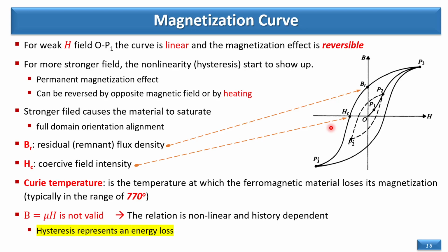Why? Because heating will cause a lot of strong random motion, and the arrangement of atoms in domains and the alignment of those domains with the externally applied magnetic field will start to be random, and once you remove the heat, everything will return to the random shape with zero permanent magnetic flux density inside the material.